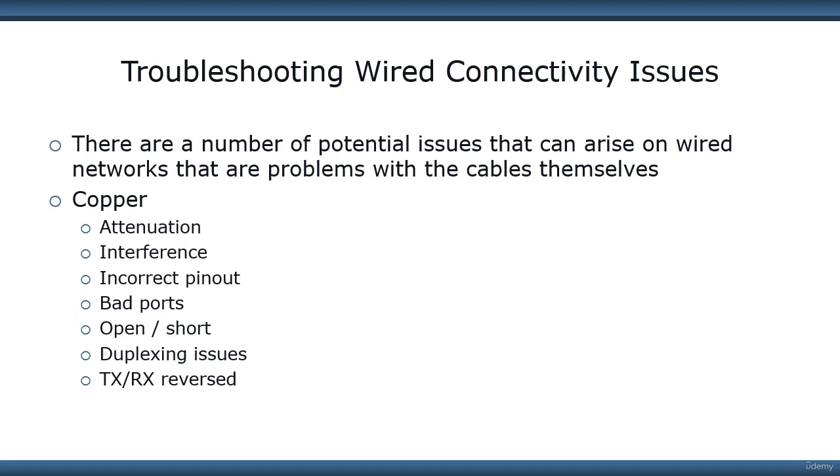TXRX stands for transmit and receive. If the transmit and receive are reversed, that's another indication of just bad wiring. Typically that would only happen if we'd actually made our own cables.